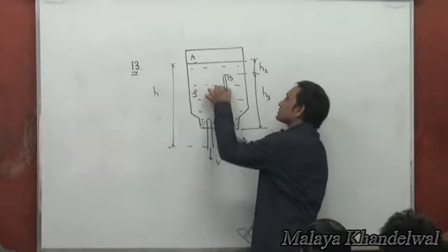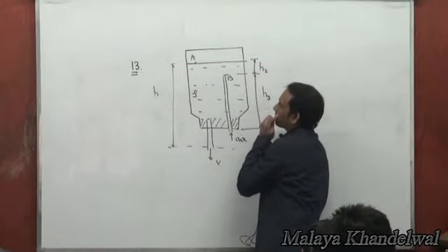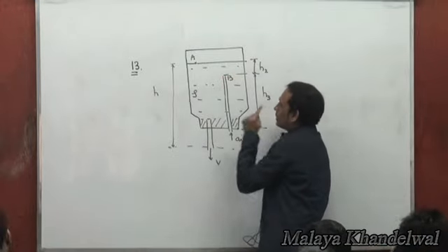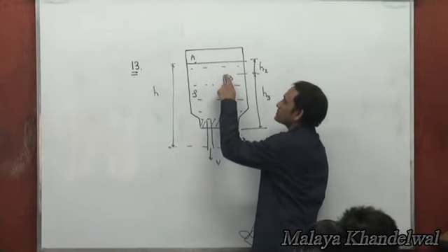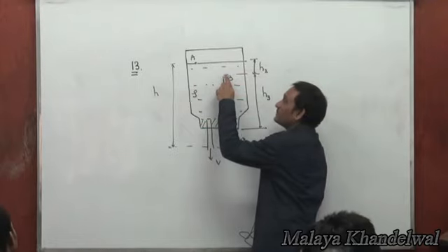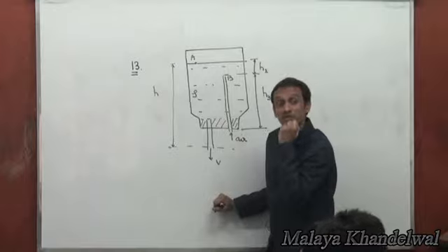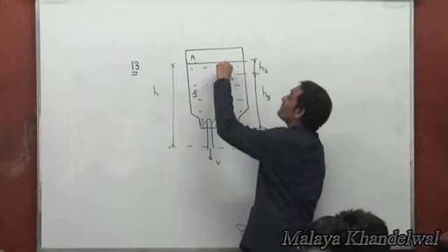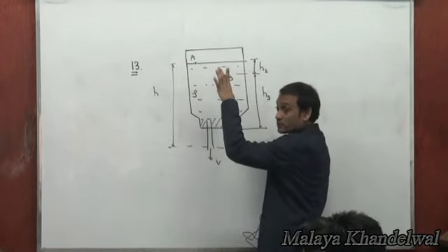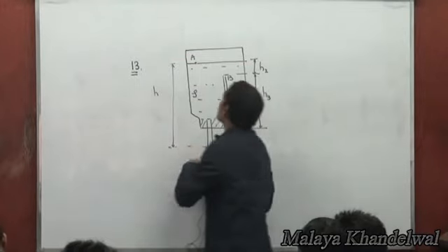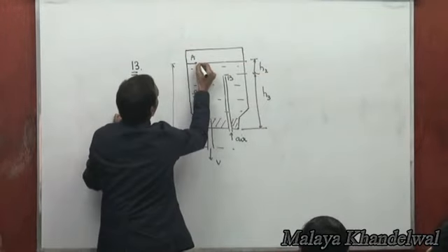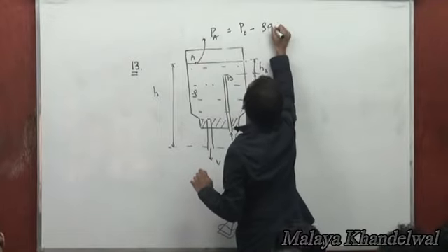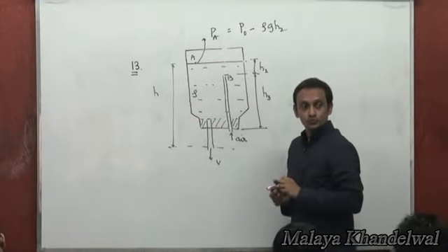Now there is a small duct. The objective of this, if this is filled in by air, what really transpires is that this becomes a region of atmospheric pressure. That means at P the pressure is atmospheric. At A therefore, that means H2 units above B, the pressure is going to be P naught atmospheric pressure minus rho G H2. So the pressure at A is going to be atmospheric pressure P naught minus rho G H, minus rho G H2.